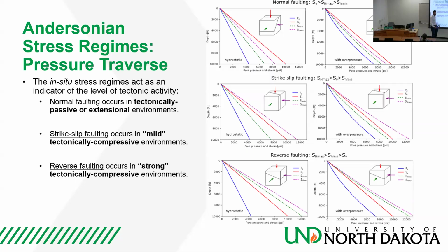So I cannot have pore pressure bigger than S3, right? Then I will have a negative sigma 3, which means that I'm lifting the rock. It can be equal at some point, but not bigger. That means I'm having net equilibrium on that side.